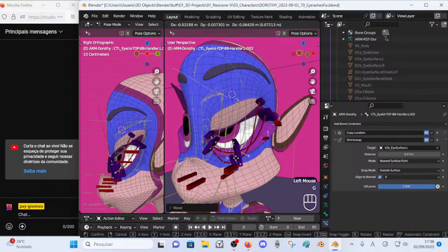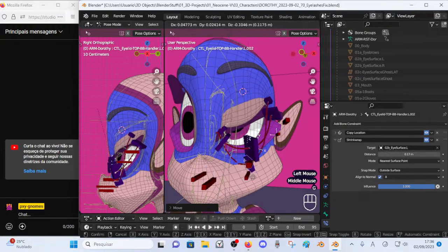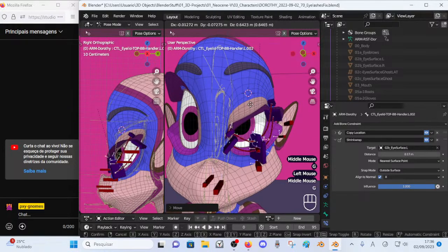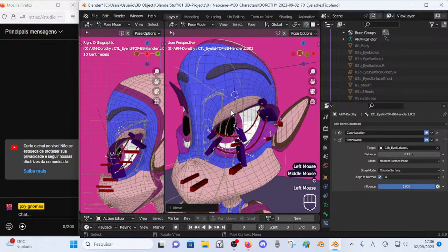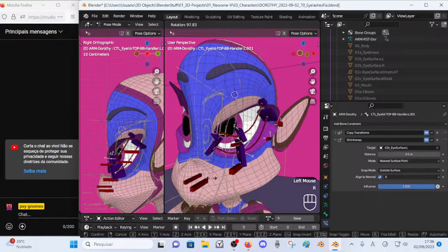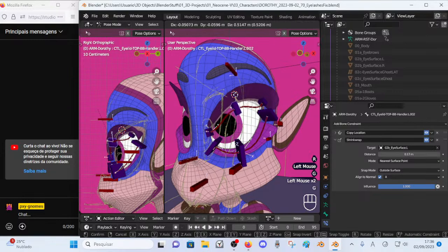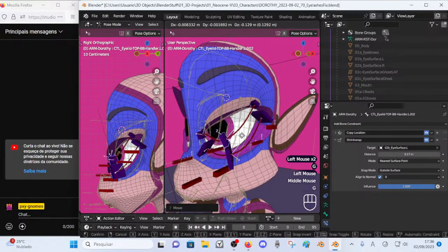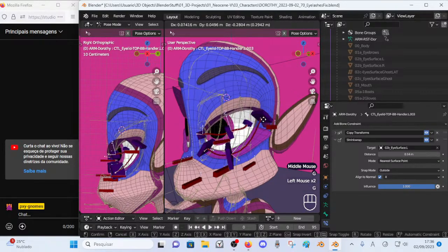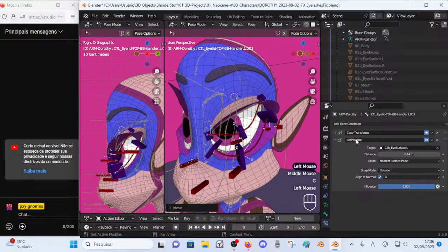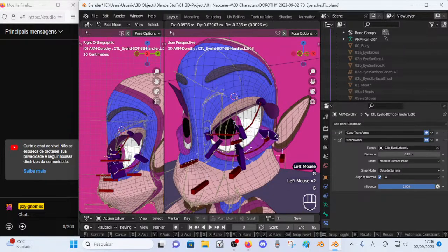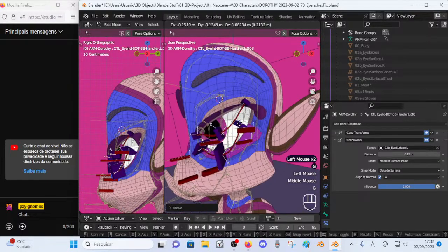So here, I cannot push the eyelid closed. So this is very bad, right? This is not supposed to be like that. The mesh is not following. Yeah, so this is actually a problem. If the mesh doesn't follow the bendy bones very closely, it can have this kind of trouble. Okay, so this is one, and the shrink wrap bone constraint is failing. This one is a little better.